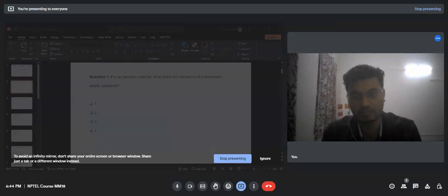This is the elastic region. This part is the plastic region. So in brittle materials, what is happening? They won't show any plastic nature. Since we are applying the stress, we are getting some strain, and at a particular point these brittle materials will break.